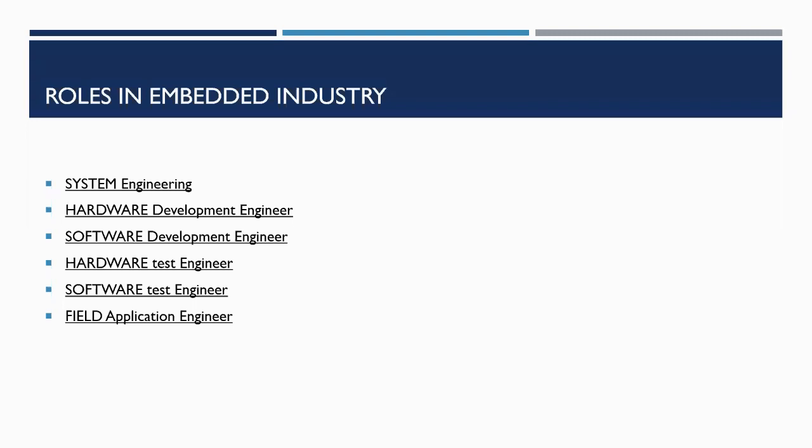So once they have understood the IDEs and the simulation and the direct hardware simulations, the next thing, it is better to study about the JTAGs. JTAG is one of the tools that helps engineers to debug. Once they have developed all the code and flashed it and they are checking whether the code is working, at some point they may see some failures. To pinpoint where exactly the failure is occurring in the software, the JTAGs will help to pinpoint the failures in the system in their microcontroller.